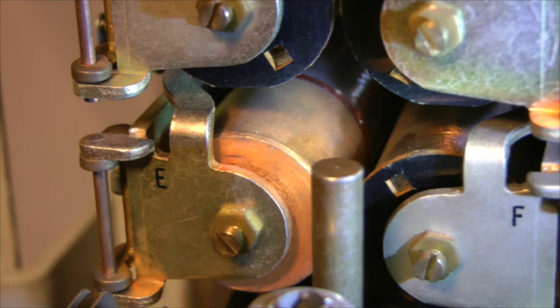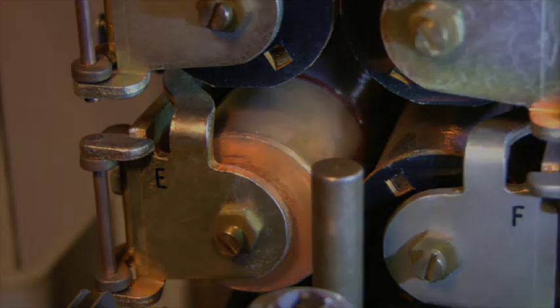E locks operated via its secondary winding and its own make contacts. This is necessary since its primary winding operating path becomes ineffective as soon as rotary stepping begins. The E relay remains steadily operated until after cut-through of the calling line to the first selector has been completed, at which time it releases. E remains released for the duration of the call.